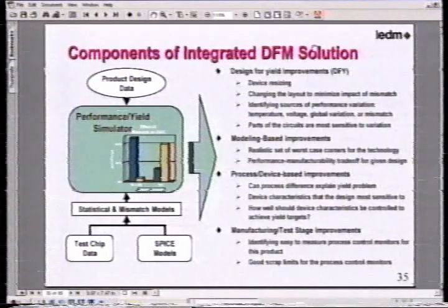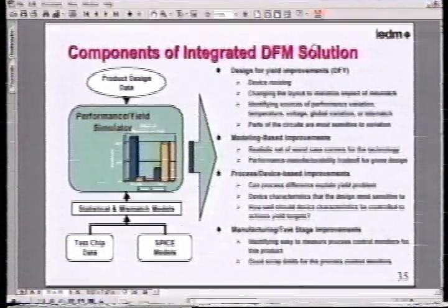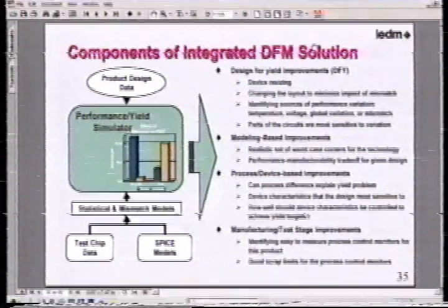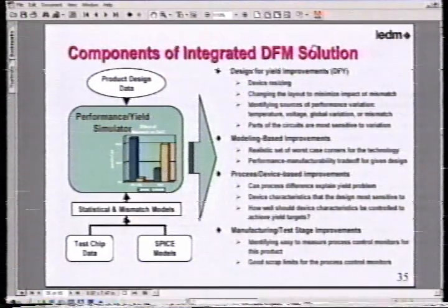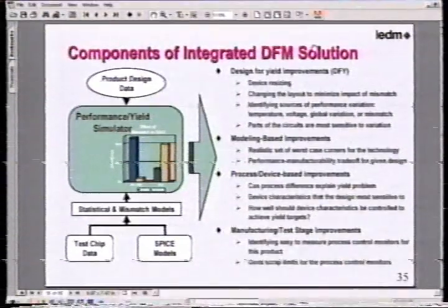All of you know that the SPICE model is the designer's definition of a device. One can simulate the product and the design if one understands the SPICE model. What you need to do is build into your SPICE model the statistics or the variations that you are seeing due to the fab. That's what makes it possible for you to get the process design interaction for the parametrics.